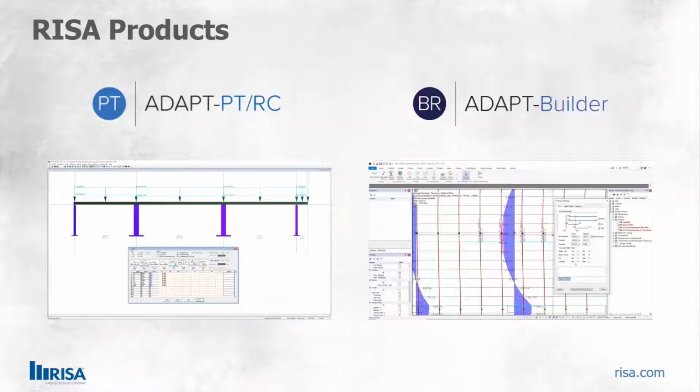Under ADAPT products, if we're looking at these two products right here, we have ADAPT-PT/RC and then we have ADAPT-Builder. These two products specialize in concrete design. ADAPT-PT/RC, the PT stands for post-tension, and the RC, reinforced concrete, is going to be your 2D concrete slab and beam design software. And then ADAPT-Builder is going to be the full 3D finite element concrete building design software. Included in the design are your beams, slabs, columns, walls, and foundations.